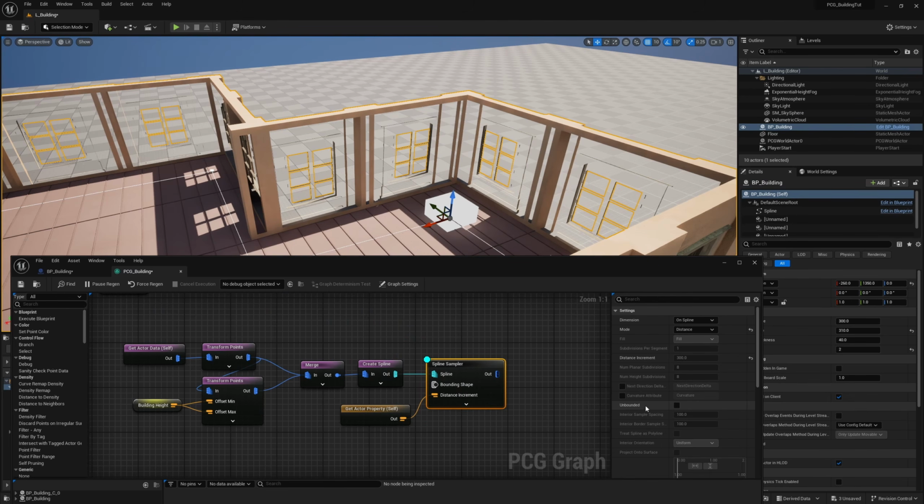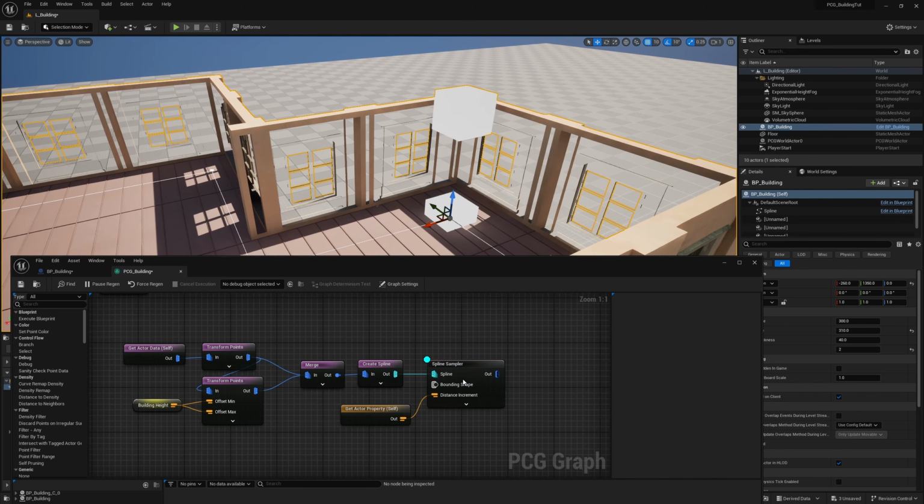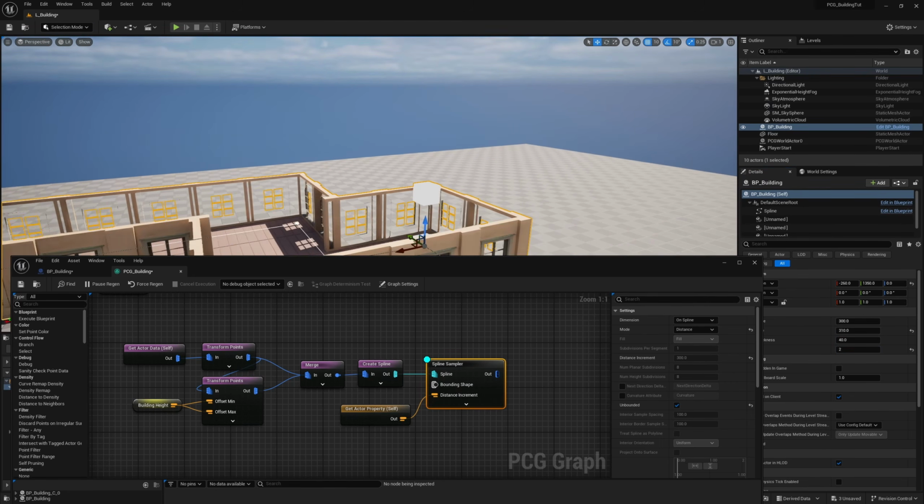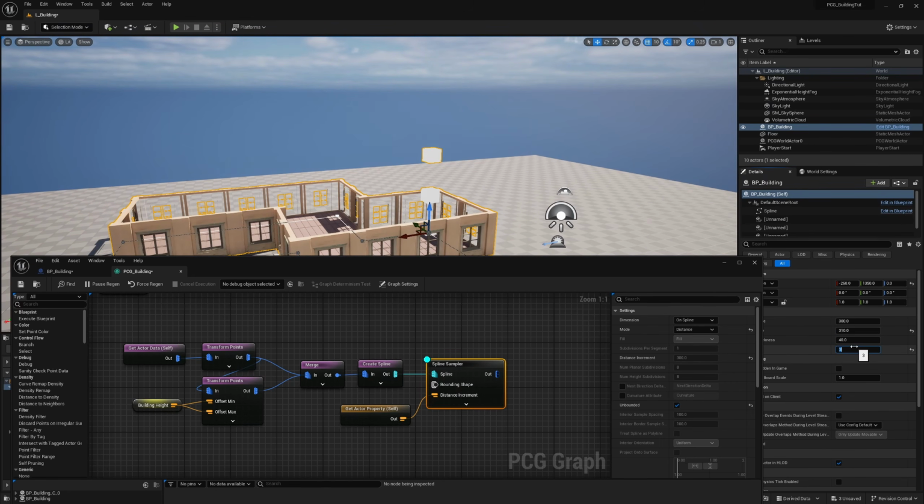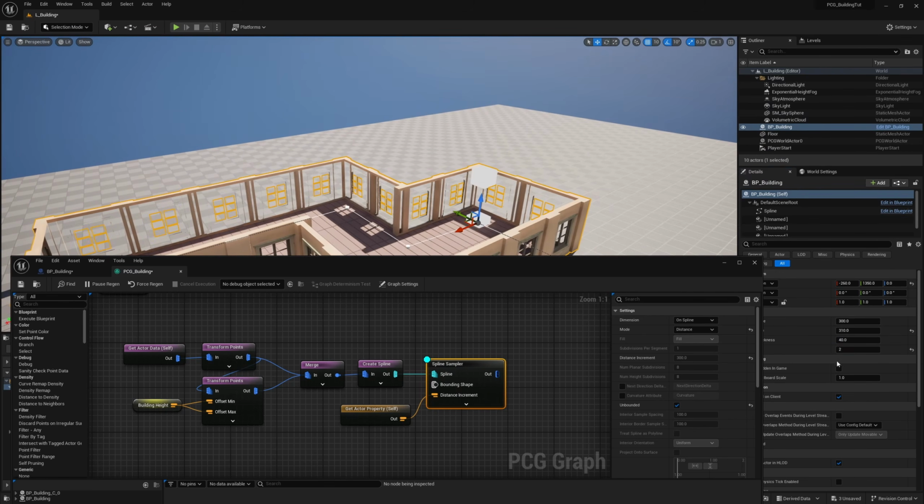And of course, as I mentioned before, you need to click unbounded in 5.3, or otherwise you do not see the actual setup. So now if I have 1, you see 1 point, 2, and if I zoom out here and I say 3, 4, 5, you can see it is now actually adding all these points as I need to. So great. So now we have kind of a setup for floors. So let's go ahead and just play around with, let's say, 3 floors by default.